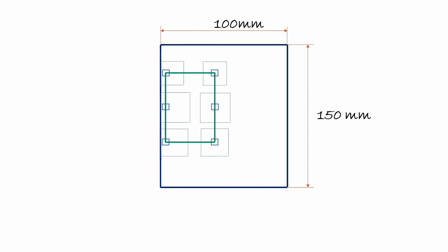Since the left side footings are the footings to be eccentrically designed, the upward reaction exerted by the soil in every footing is in this location. If we cut a section on this side, since the soil's resultant reaction force in this footing is directed upward, it will create a moment on the column directed counterclockwise. Therefore, we apply a moment at this column and the direction is counterclockwise.